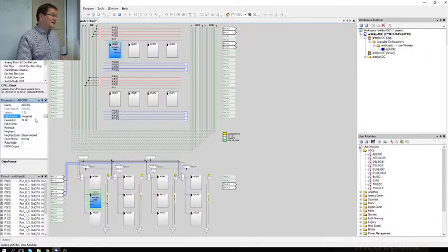Practically, the unsigned representation is good for unipolar signals, and since this PSoC is actually running at 0 to 5 volts, I would always use unipolar and later on do the calibration if needed. Okay, resolution. Again, for clarity, I'll take 8 bits. That fits nicely in 1 byte.